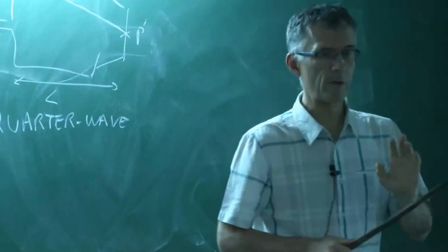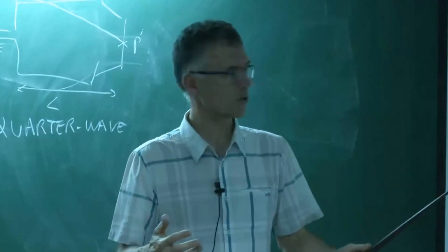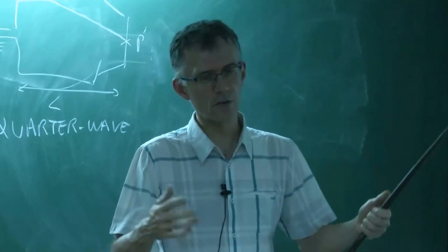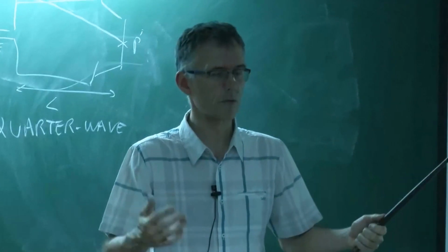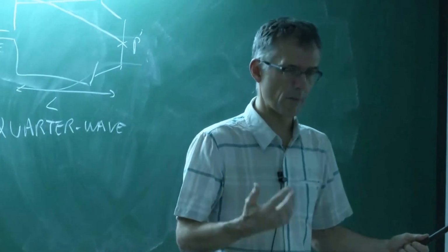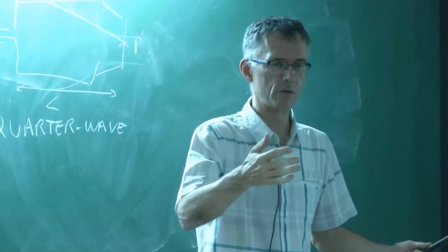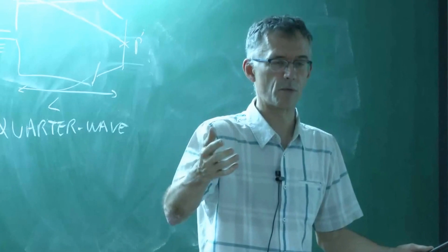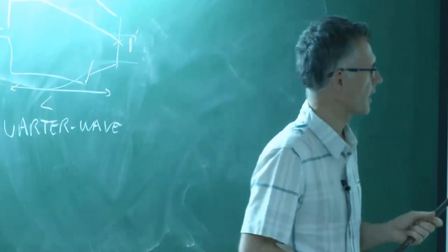Acoustic codes, we will freeze the flow. That really means we suppose that the Mach number is not very large. And in most cases, it's not bad. I mean, most Mach numbers in chambers don't go beyond 0.2. So the correction of the Mach number on the acoustic modes is in Mach squared. So if you have a 0.2 Mach number in the flow, that's a 4% error on the frequency. That's okay. We can live with that.